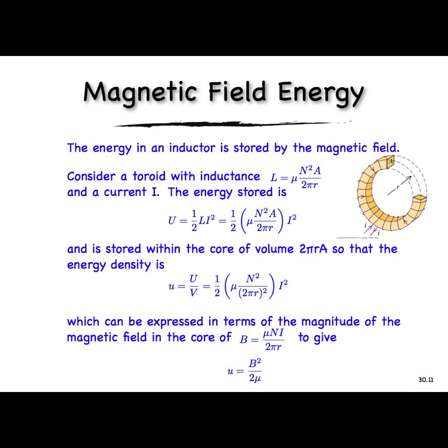So where did that energy go? I already said it 1 minute ago. Not heat. If it goes to heat, it's lost. It's stored somewhere. We can get it back. We will get it back if we take this circuit that was pumping current through the inductor and I suddenly remove the battery. The quick change of the current will produce an EMF that can continue to power the circuit briefly. So the energy is stored and can be retrieved.